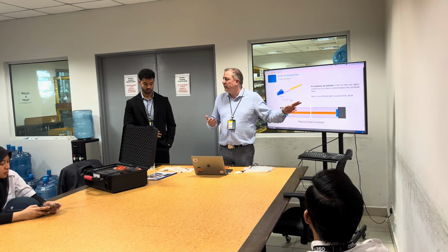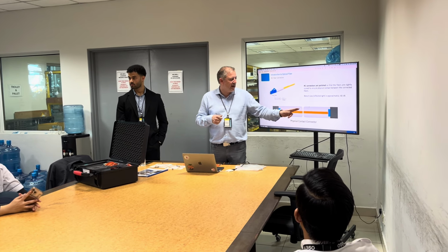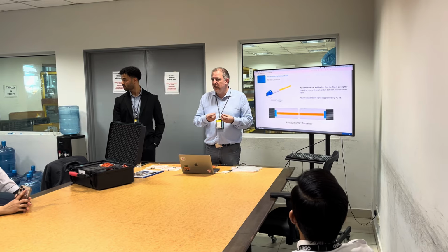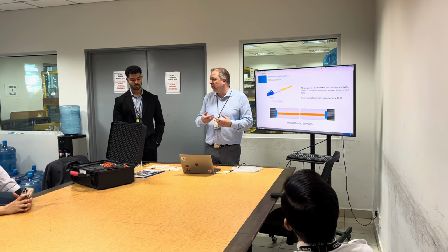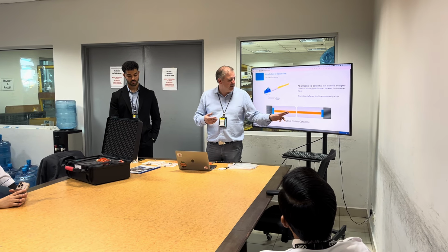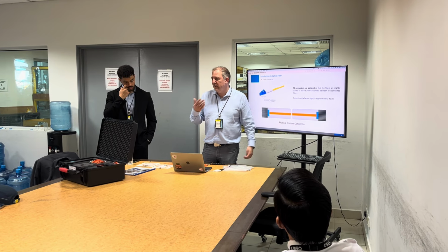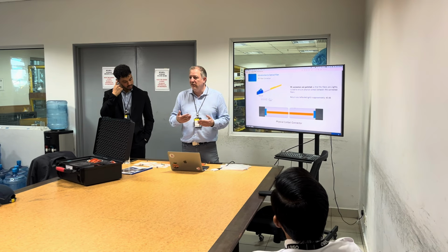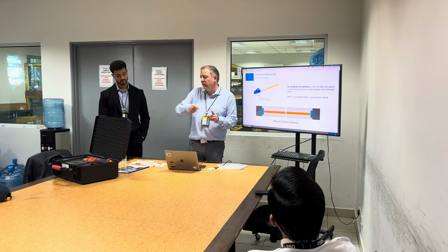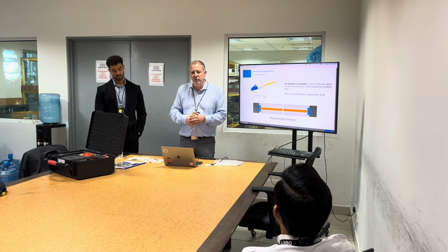If you have some dust inside, most probably when you connect, you may scratch this part. It's not perfectly polished anymore, and then you lose some light. So every small damage, every misalignment, every air gap in between is a source of a bad connection, and if you have one or two on the way, you don't have enough power at the end, so the system is not working anymore.